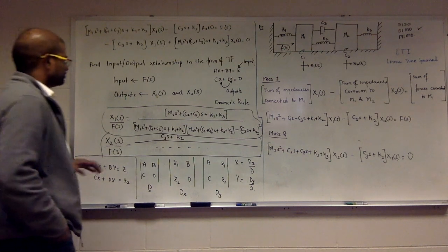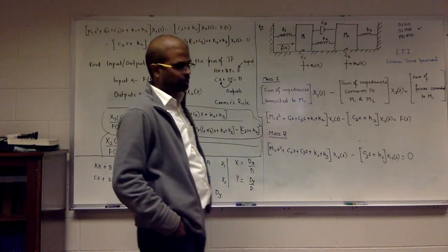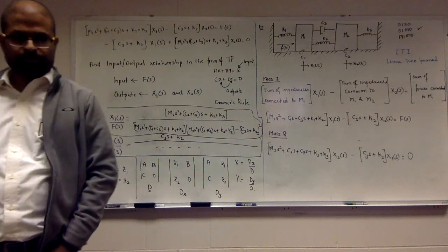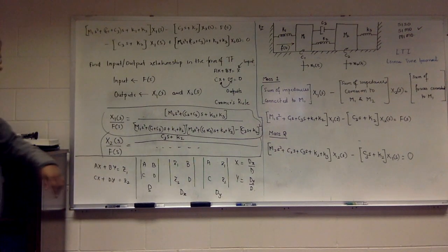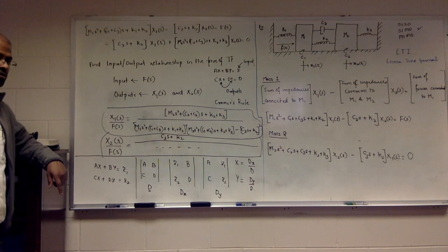So you cannot just say M1, M2 are constants. They will change as time progresses. That's a very critical component of an aerospace system, that mass changes. But what you do is approximate. If you want to apply basic control theory, you linearize it. You say from this time to this time we assume this mass, and then from this time to this time that mass. That is piecewise linearization.